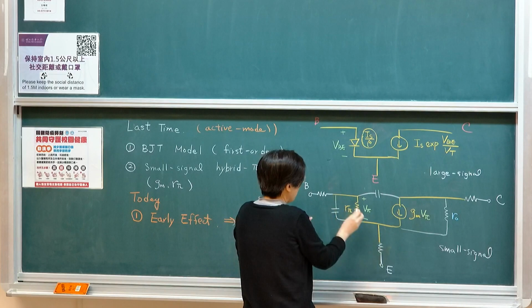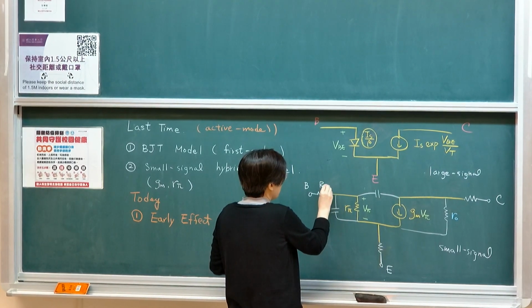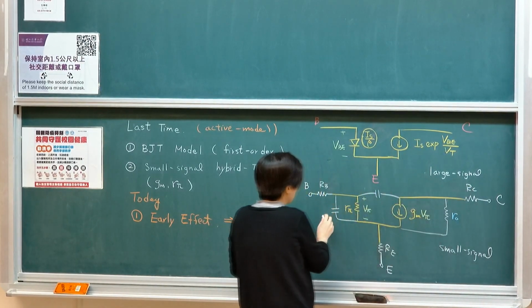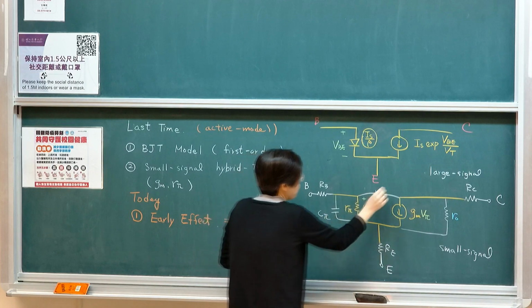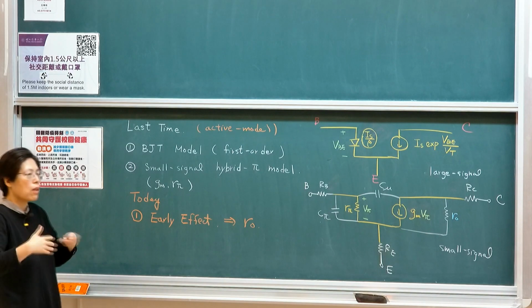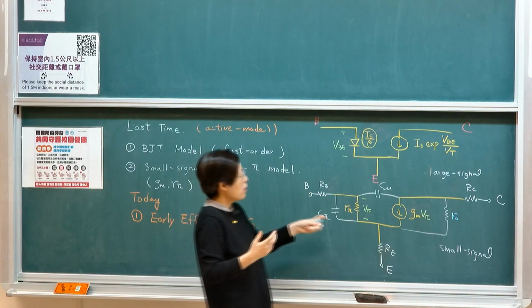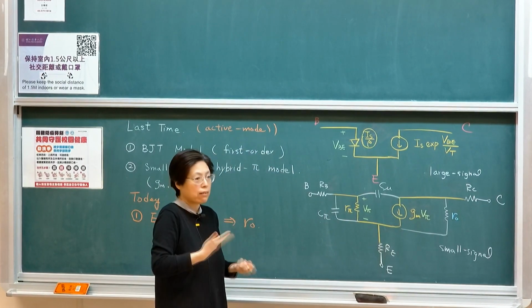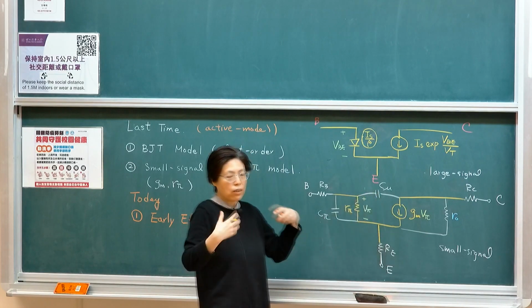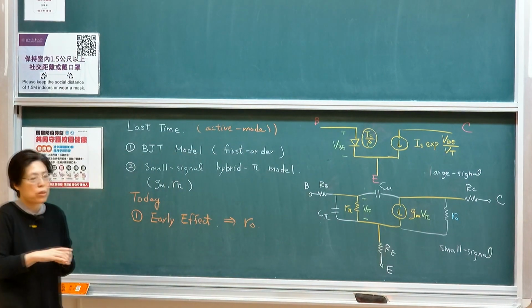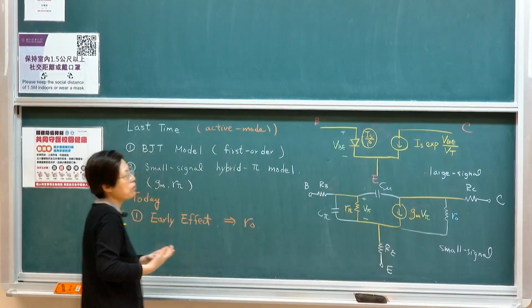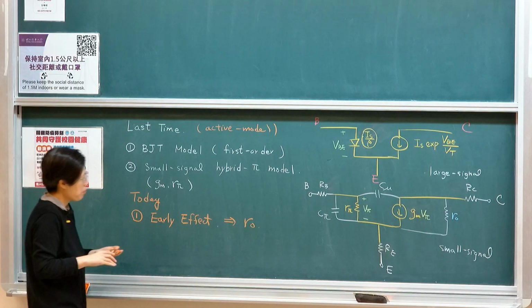These other parts are parasitic resistances r_B, r_E, r_C, and also parasitic capacitances C_pi and C_mu. We'll discuss those when we talk about frequency response. When we discuss how fast the transistor can transit, then these would count. But if you're ramping your transistor at a very slow speed, whether they are carrying a bucket or not doesn't make much of a difference. But if you're considering speed, then these buckets would delay the speed of the operation.